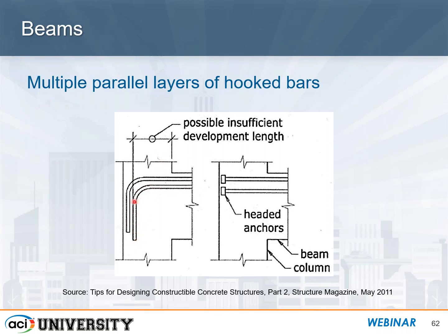It's possible that these bars on the inside here may not be able to be developed properly. That occurs when you have these larger bars, number 8s and 9s, and trying to hook those big bars and maintaining your development length may not be possible, especially based on the size of the column that these are being embedded into. So one possible solution for this is to use a headed anchor.